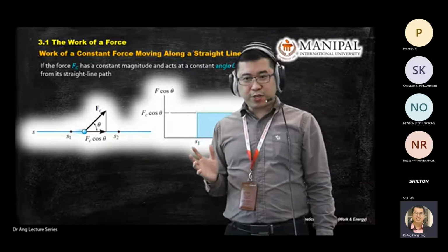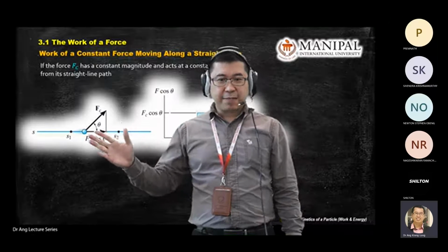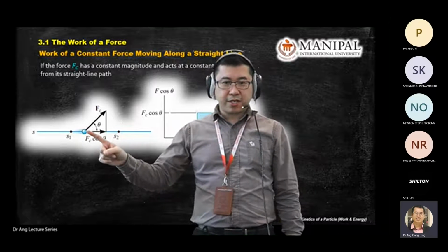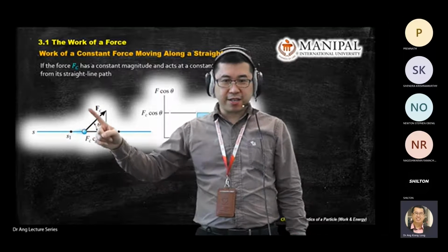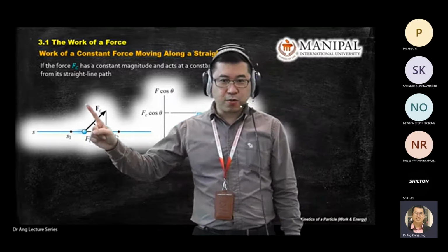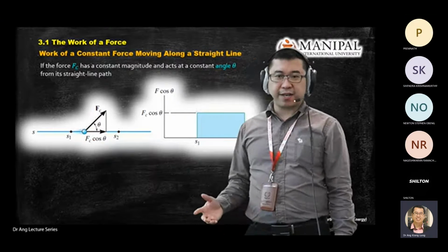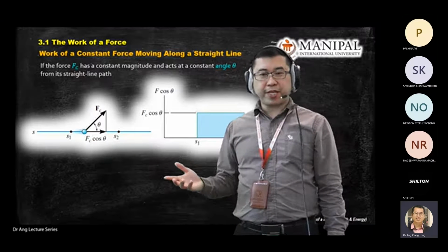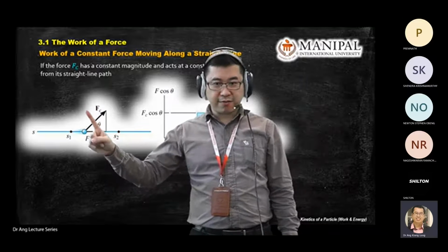In solving questions in engineering dynamics, sometimes you need to draw the vector component there. In this one, I will remove the y-axis because I want to emphasize how work is done. But when you draw a free body diagram later on for questions, you still need to draw the vertical axis.